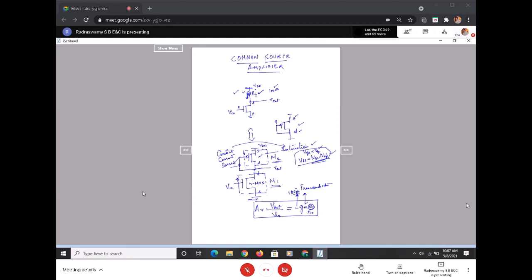Later I will ask you why this 180-degree, and this R0 is something like a load resistance now. This is the expression for gain. Can anyone derive this gain expression for me? This is typically for the M1 transistor, because that top PMOS is just a resistance for me. That's it, a fixed resistance with a constant current supply.